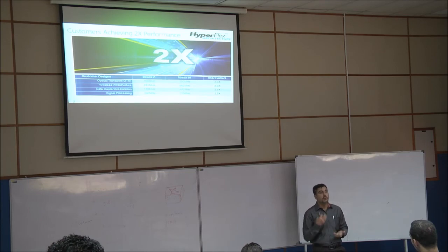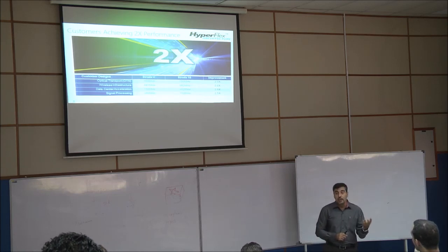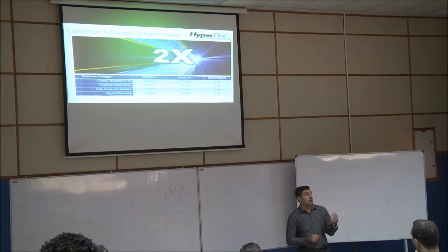What we have to do if we want to divide the frequency? We have to use the flip-flop, right? So if I enter 50 meg to one flip-flop, the output becomes 25 meg, right? So divide by 2. Each flip-flop divides by 2. So if I want to divide by 8, how many flip-flops do I need? 3. 2 to the power 3 gives you 8, right?